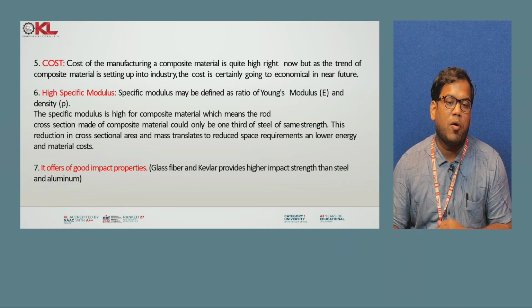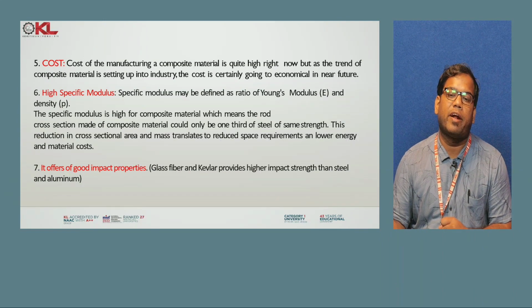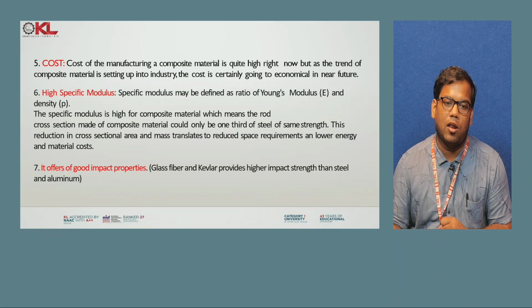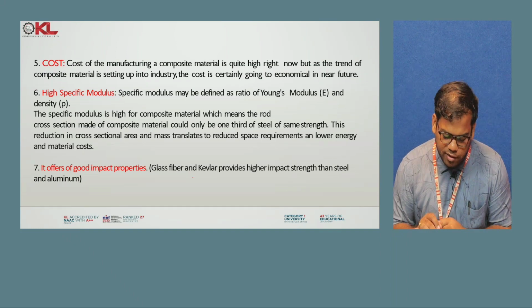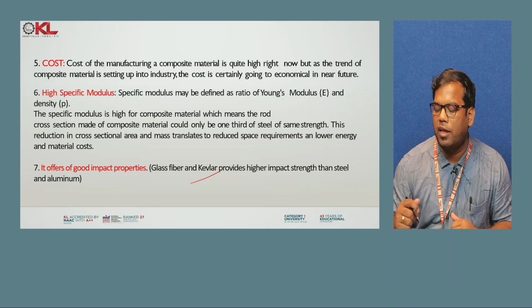Similarly, good impact property: glass fiber and Kevlar fiber provide better impact property than steel and aluminium. Kevlar fiber is very much used in bulletproof jackets in defense application.